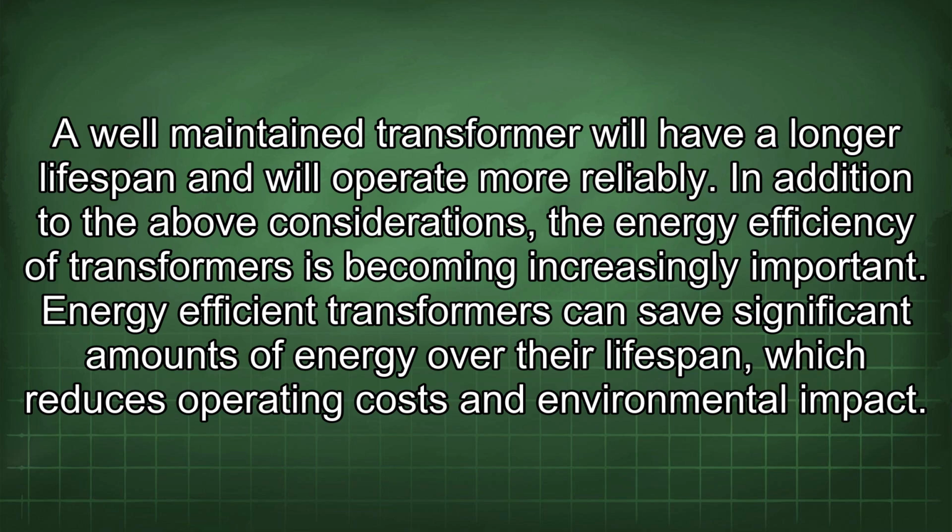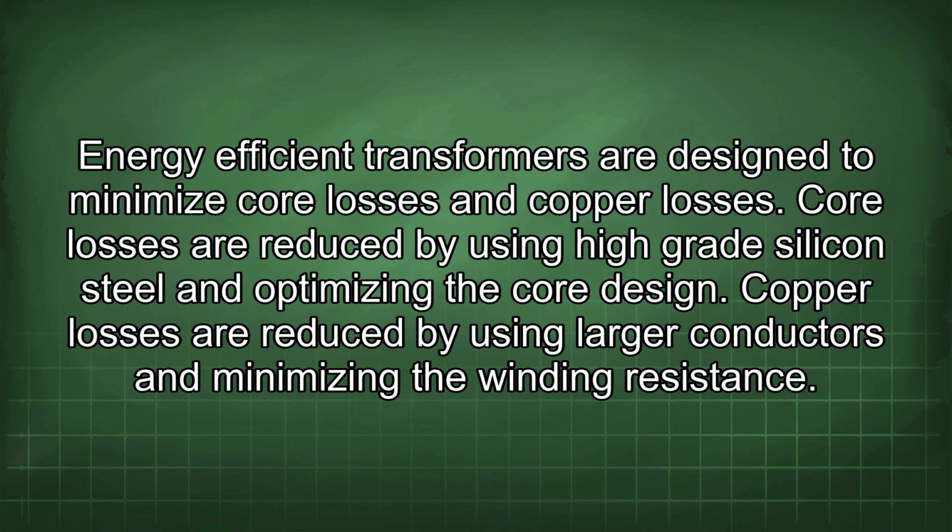In addition to the above considerations, the energy efficiency of transformers is becoming increasingly important. Energy-efficient transformers can save significant amounts of energy over their lifespan, which reduces operating costs and environmental impact. Energy-efficient transformers are designed to minimize core losses and copper losses. Core losses are reduced by using high-grade silicon steel and optimizing the core design. Copper losses are reduced by using larger conductors and minimizing the winding resistance.